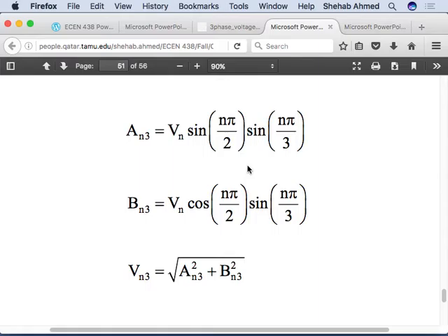So even if you have low harmonics, but if they correspond to a resonant frequency in your system, the generator's resonant frequency, the transmission line's resonant, whatever, if any resonant frequency in your system, you have to, that's why when you design any mechanical system or electromechanical system, you have to know the resonant frequencies of all devices in your system.